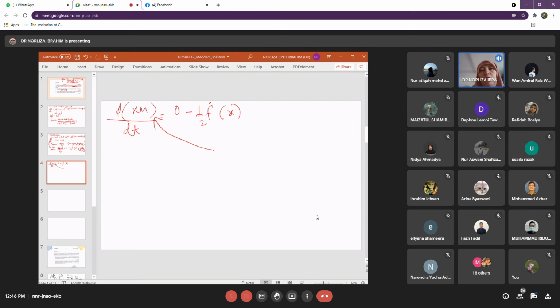We have to think of whether your fraction changes with time, whether your m changes with time. The previous example is d(V CA): volume changes with time, CA changes with time. So you get V dCA over dt plus CA dV over dt, because both change with time. So if you expand this expression, it will be this way.